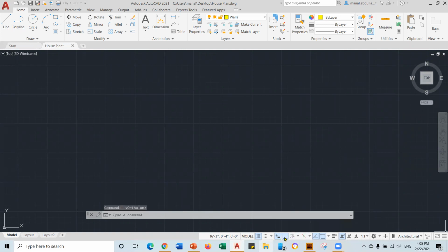As you see here, you cannot put them together, because if you make the ortho mode on, the polar tracking will be off. Dynamic input, it's up to you. You can put it on or off. I will turn off the snap mode. I don't need to snap on the grid, so I'll turn it off. Also, I'll turn on the display grid. So let's get started right now.